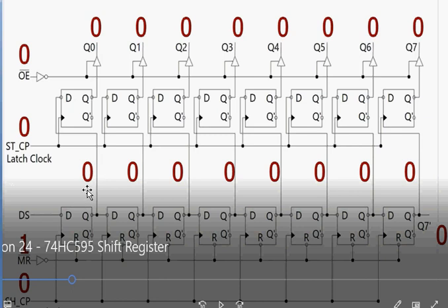Now let's assume that the next bit is 0. You have to shift the data using some methodology, some program. Then you get 0, and that 0 will be over here now. Again, to get that data onto this end, you provide 1. Previously you had 1 here. So when the clock pulse is given, during the rising edge of the clock, this 1 gets transferred here, and the 0 on the data line goes to this end. So you get 1 here and you get 0 here.